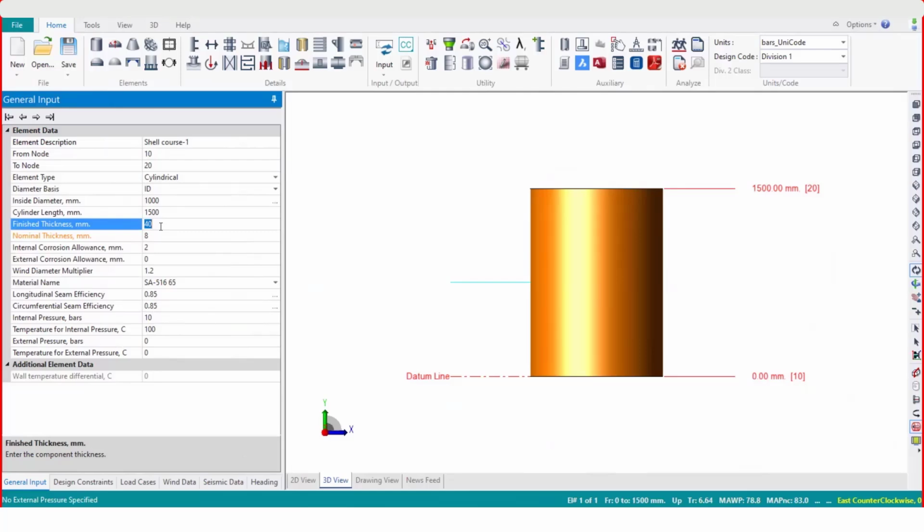So when you are going to do the rolling operation, have you heard about rolling? You will be taking one flat plate and passing it through the roller, and it will change its shape to circular. That is called the rolling operation, by which your cylinder will be manufactured or prepared, right? In that rolling procedure, there will be no reduction in thickness.